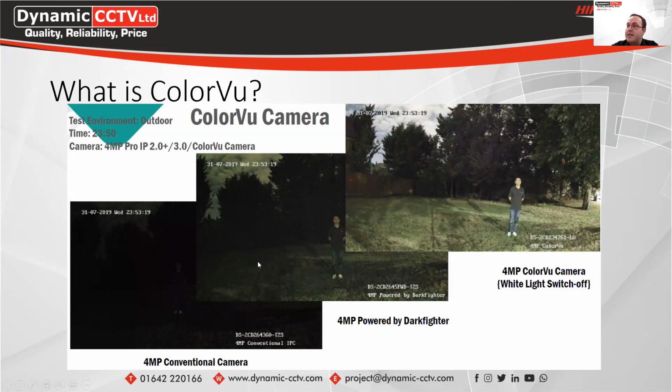So that's on the middle image there, that's a dark-fighter image. And then the one on the right-hand side is a ColorVu image. This is without the white light LEDs turned on the actual camera itself. So this is just using the ambient lighting in the area to give you that image. That's using no additional lighting. And on the far left-hand side is a conventional camera in the same scenario without any IRs enabled on the camera. You can see the differences when you're using the ColorVu cameras, which makes it a great camera, especially if you're wanting to stay in color 24/7.